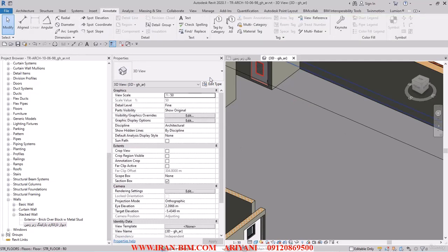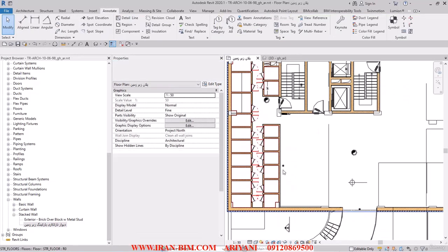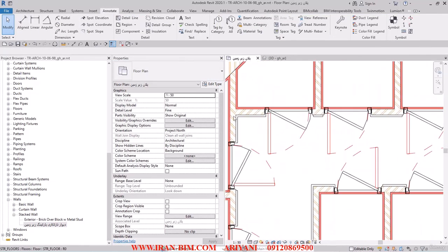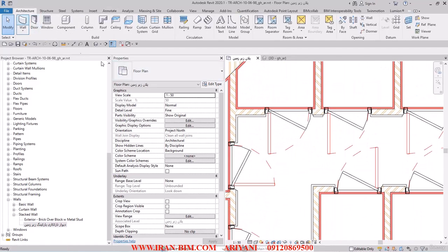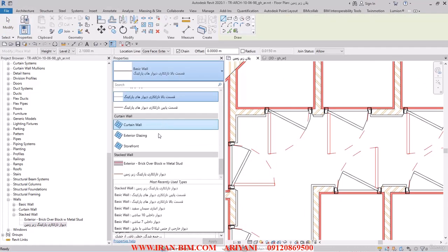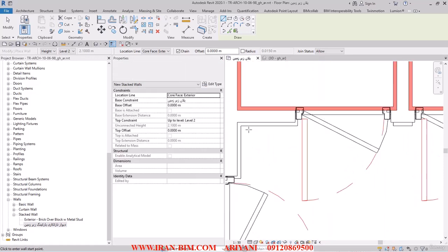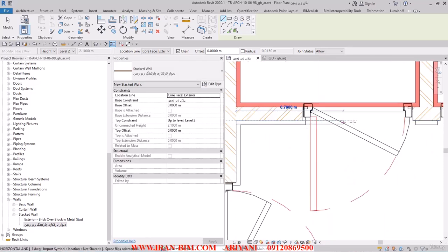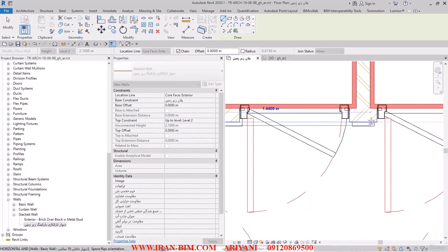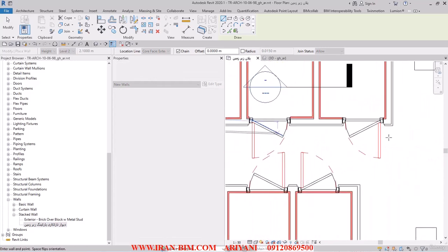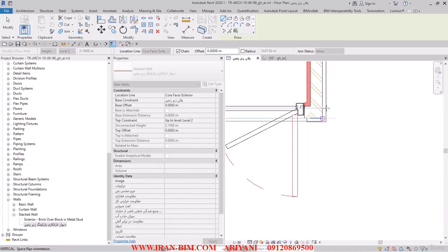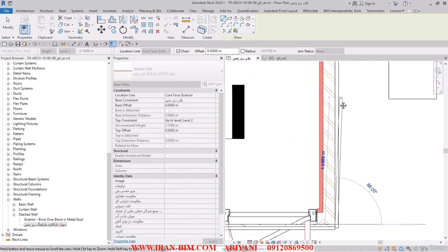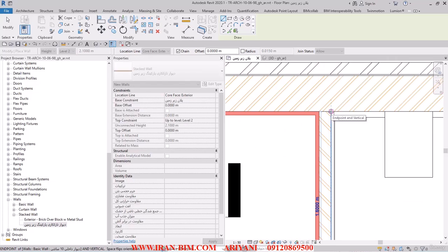And then let's go to the underground planning. So this is all for the parking section. Let me just select the wall. And then we go to the stack wall part here. And then I'll start drawing the wall. So we grab this one and then we draw it up to this point here. Then from here we start again. And there we go to this point.